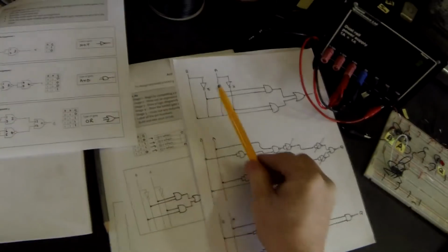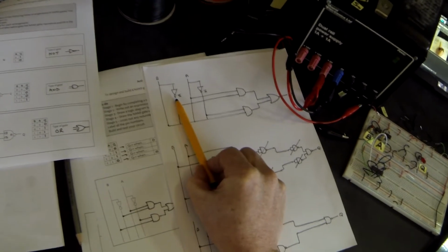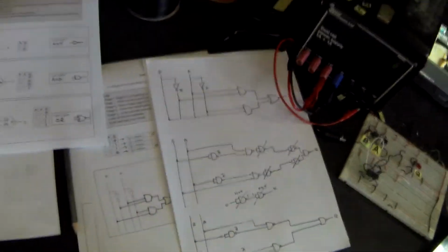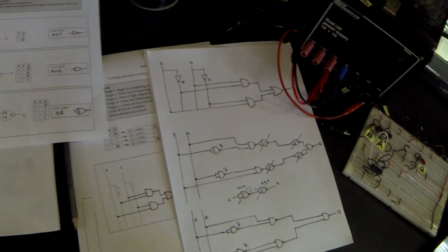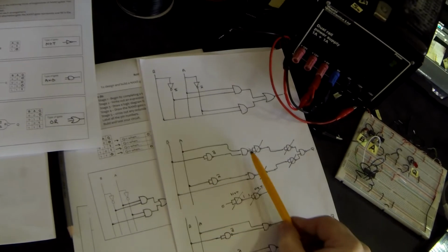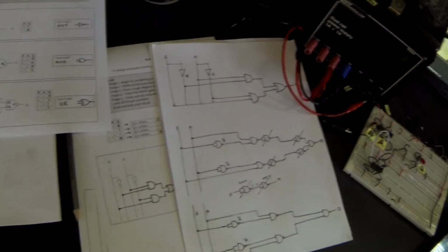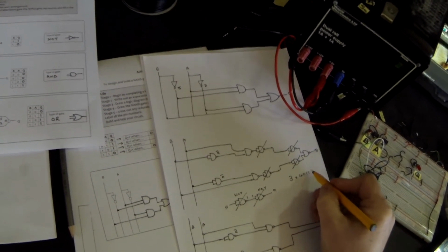If we go back to the beginning, we began with a NOT gate, an AND gate, and an OR gate. We were using 3 separate ICs in that circuit. In its NAND gate equivalent circuit, we were using 1, 2, 3, 4, 5, 6, 7, 8, 9 gates, which would have meant that we used 3 4011 chips.